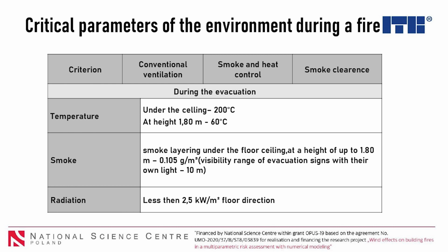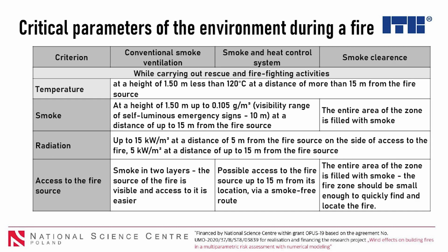What I would like you to look at is one of the levels of the car park. The one on the left is fully covered with cars, so all the car locations are filled. The picture on the right side is the car park without cars, but with the same number of people. When we start the calculation of evacuation and compare both times, you can see that the evacuation time in the car park with cars and without cars is more or less the same. It's only 3 seconds of difference.